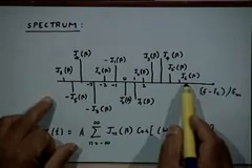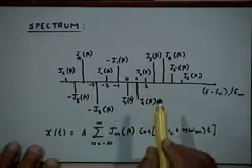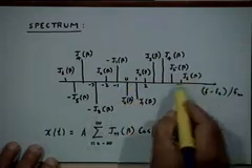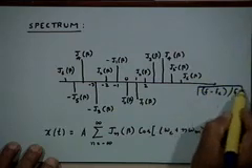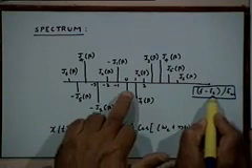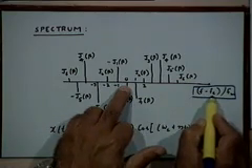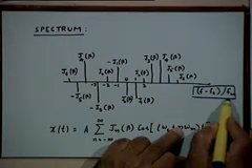use this in association with our discussion earlier, a typical spectral plot of an FM signal would therefore look like this, right. This is the frequency axis, where I have chosen the frequency axis to be normalized. I have looked at the frequency deviation from the center frequency Fc, normalized with respect to the modulating signal frequency Fm.